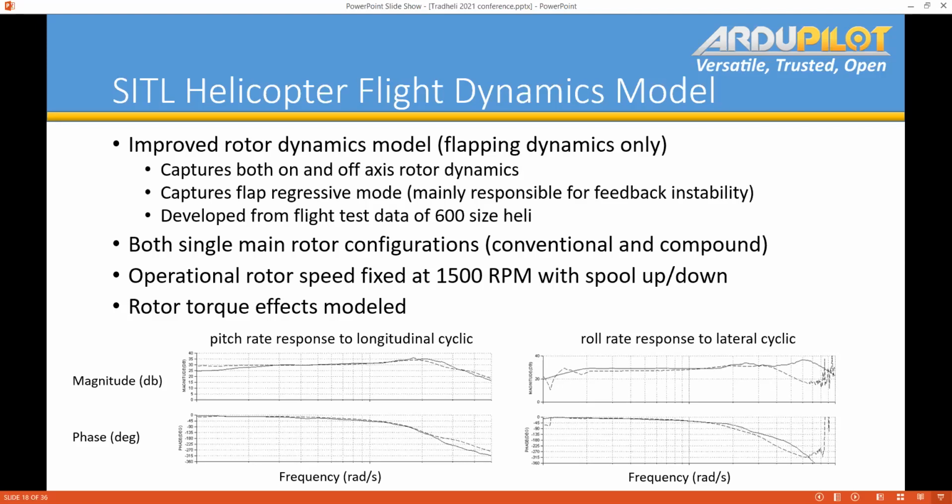Well, it kind of falls out from the frequency response for the aircraft configuration. I did one for a multi-copter, and in the class I took on CIFER, I learned about the dynamics that it can't see. What you learn quickly is that multi-copters have fairly low damping because they're effectively unstable if you don't have any help from a flight controller. But when you do the frequency sweeps, that falls out of this methodology.